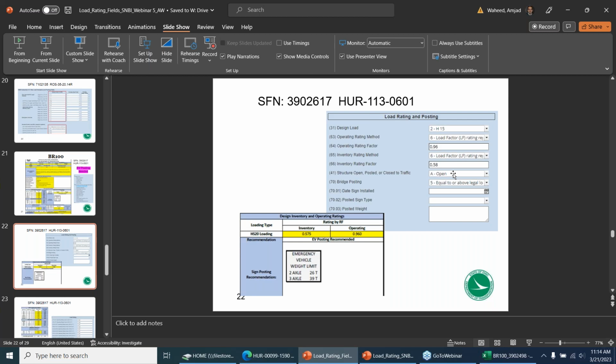Great. Next question. Do all non-ODOT bridges need to be updated with the AASHTO loads? Type 3, 3S2, 3-3. Answer is yes. The SNBI requirement is for all the bridges which carry public roads. So public traffic, whether they are muni roads, county roads, township roads, any bridge which is carrying the public traffic and the data is submitted to FHWA or it is in AssetWise, that requires to be done.